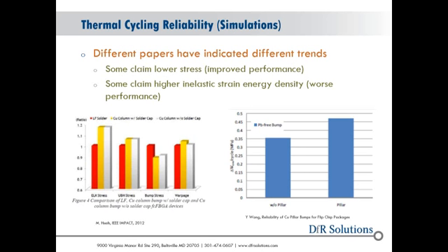And they're saying, look, the stress with lead-free solder, the bump stress, is a 1. So this is all normalized. The bumps are a 1. If I go to copper, I'm going to increase the ELK stress, but there's ways around that like we talked about. I'll increase the UBM stress slightly. The warpage is pretty much the same. But look, I greatly reduce the stress in the remaining solder, the bump stress. So they're claiming that we're going to have better reliability with copper pillar.